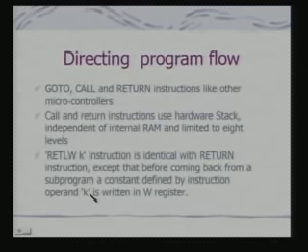So, you are returning a particular value from the subroutine call using a single instruction. This instruction enables you to return a value in the W register, and this leads to very interesting tricks that you can play with your code, and we shall see such examples now.